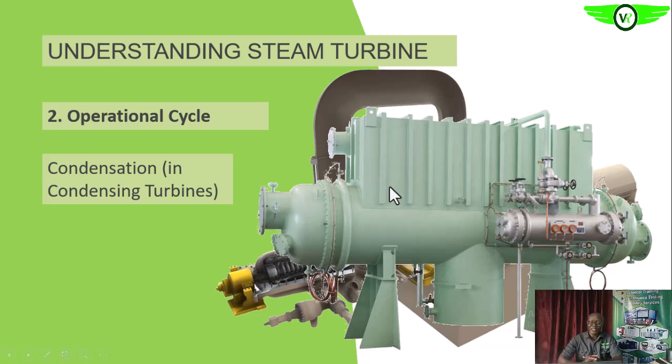But the thing is that the possibility of us having non-condensable gases within the system, even if your deaerator is very effective. The possibility of having non-condensable gases, okay, within the steam will be there. That may be as a result of leakage or poor water treatment, or ineffective water treatment. But the non-condensable gases must be there.